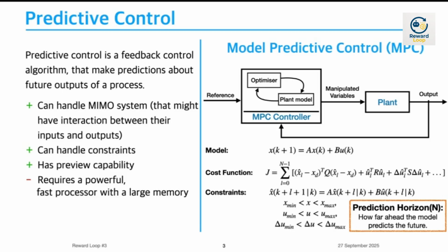For example, the first term of the cost function is (x minus x desired) transpose Q (x minus x desired). It is an attraction force towards a desired position where we would like to send a robot. It can be set point control, or the desired position can also come from a designed trajectory. The second term, u transpose R u, can also be read as (u minus 0) transpose R u. It says that my control input should be as close to 0 as possible.